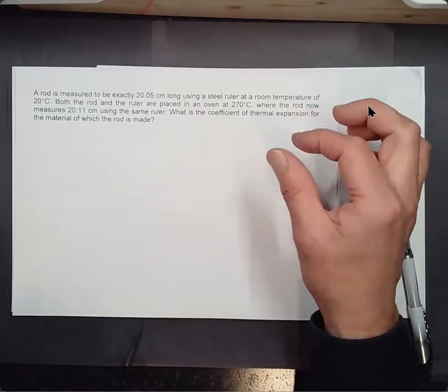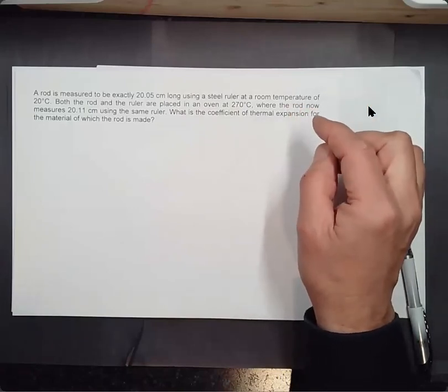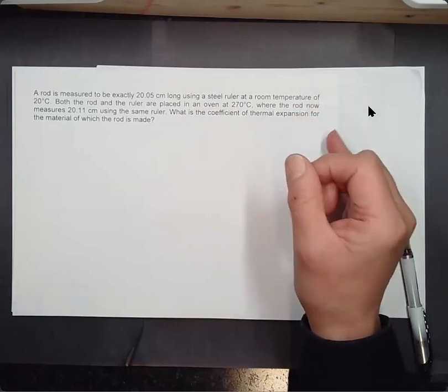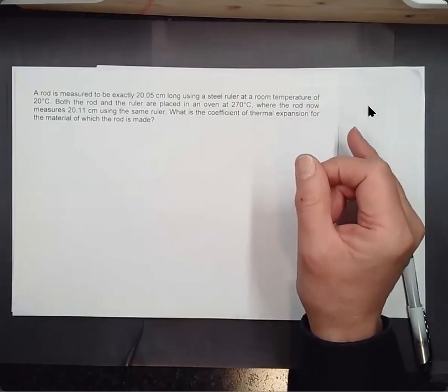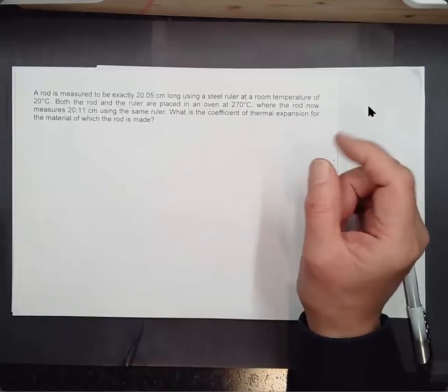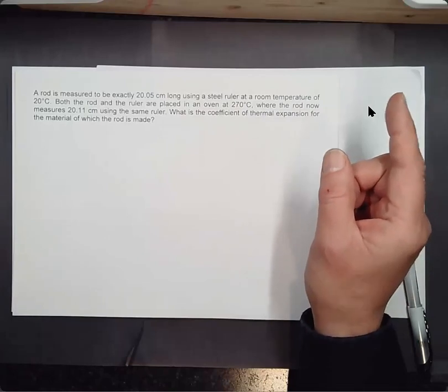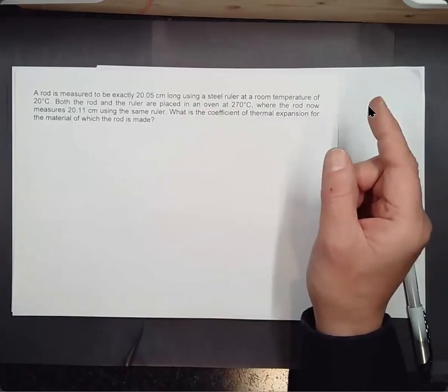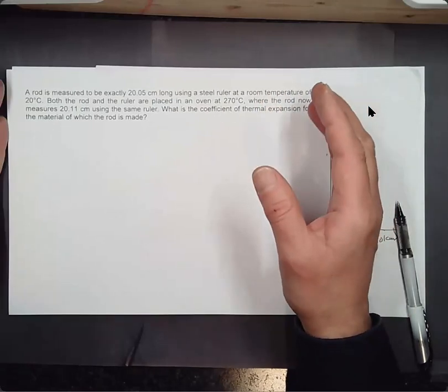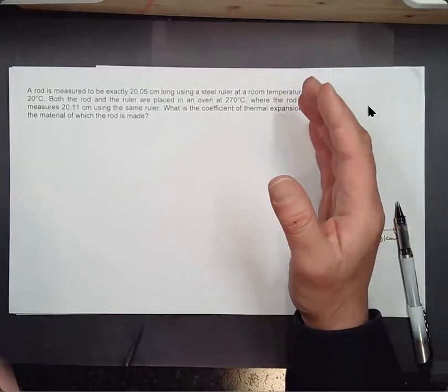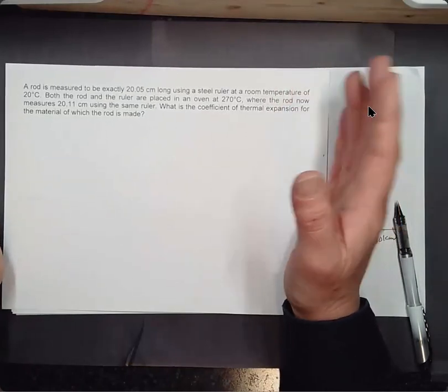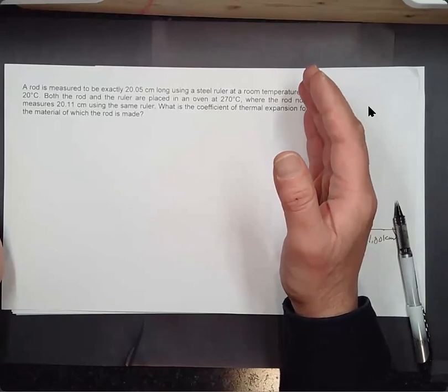The device can measure the change in length of the rod to within 1/100th of a millimeter. We measure the lengths of the rods before putting them in, then expose them to steam, get their temperature up to as close to 100 degrees Celsius as we can, and see what the change in length is.